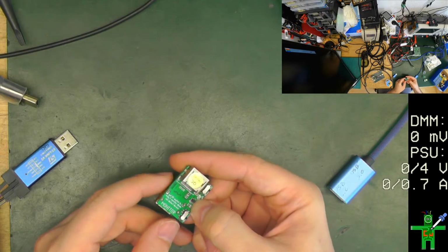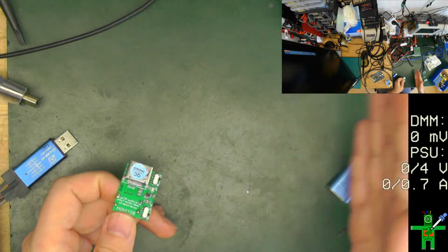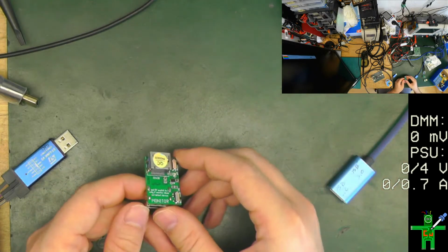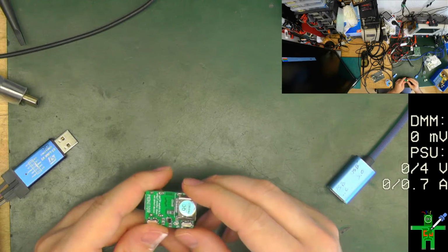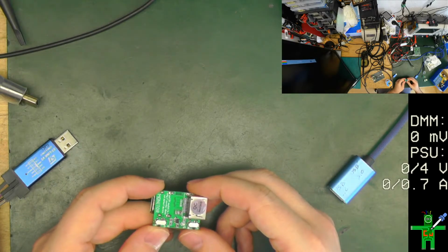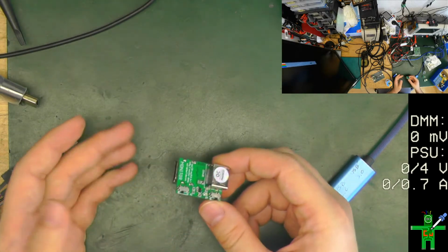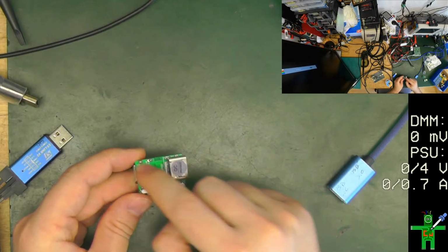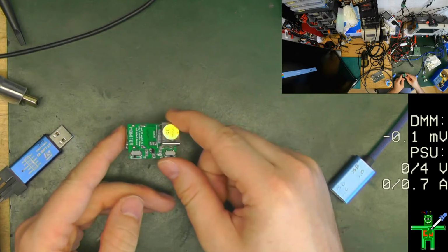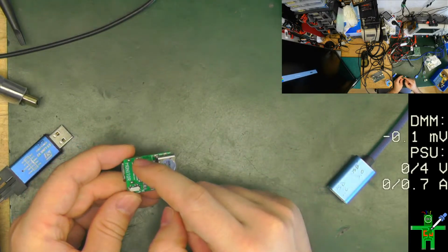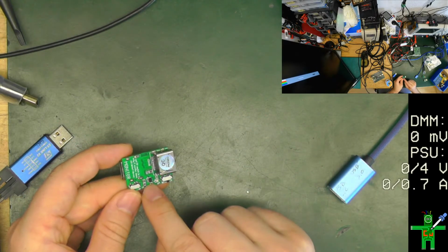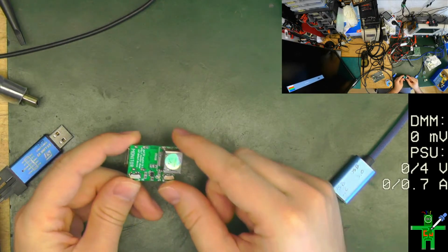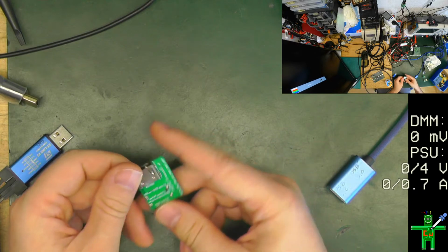There are some cases where the EDID information can have lots of extensions, and if it has more than one extension, just an EEPROM won't work. In most cases, it is just an EEPROM because I have never found anything which has more than one extension. So in this case, we just forward the data traffic. This was the first version. You just forward the video and audio lines, and the EDID information is stored into the EEPROM here. And this worked. This was version 0.